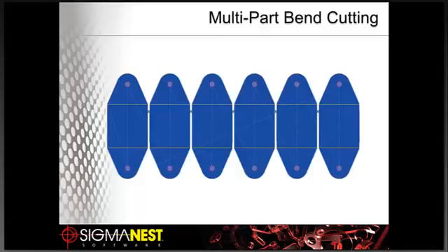The concept and the idea of this is to generate a row of parts with a bridge cut in between there. And then we're going to stick all of these parts in the press brake at one time. And that eliminates some time set up for secondary processes. So instead of having to bend 6 of these individually, we can do it at one time.